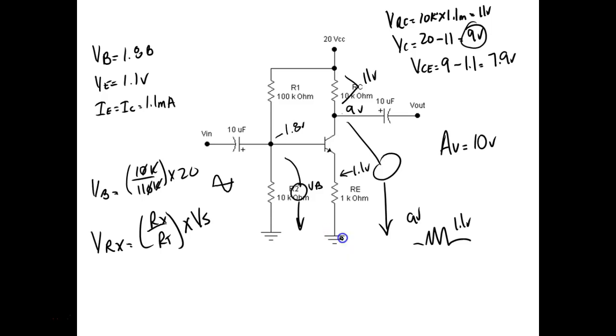So I could come up here and put my meter right there and measure on that resistor, and I can measure that right there without trying to get my meter leads in across that transistor. Now, what's the problem with that? Have y'all seen these little transistors, how close those leads are together?